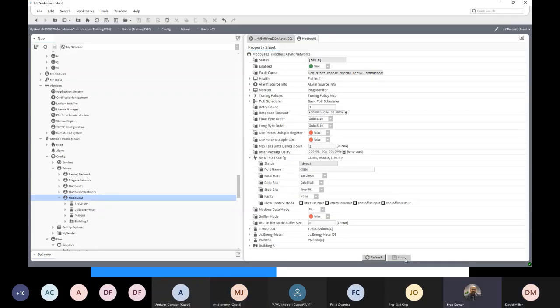Coming back to the earlier question on how many protocols, for example, on one IP port I can have BACnet IP, Modbus IP, KNX IP, there's no issues. That's right. The IP network is different from the RS485. The IP network can allow lots of different protocols, all sharing the same network. And what's different is that every IP address has a port number.